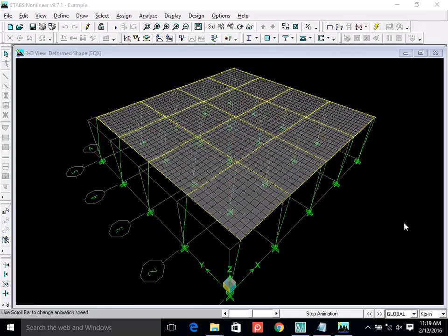For example, if the building is under construction and it is not in use, then in that situation it's only dead load and earthquake. Or for example, this department in the evening, there is no significant live load, then at that time it's earthquake plus the dead load, including part of the live load, which is furniture, of course.